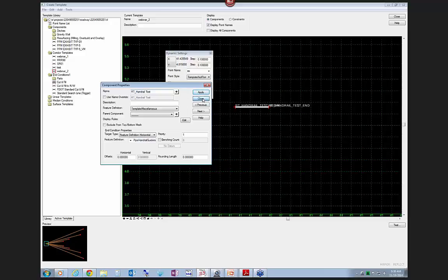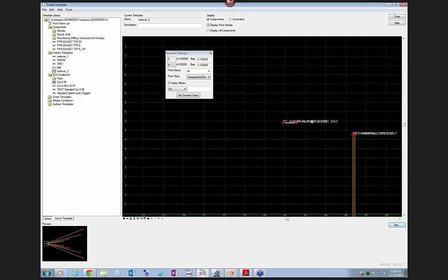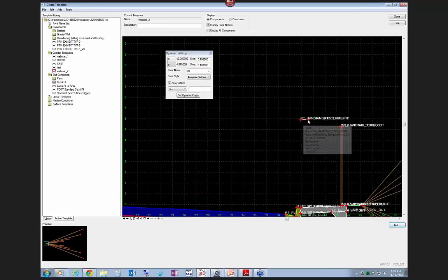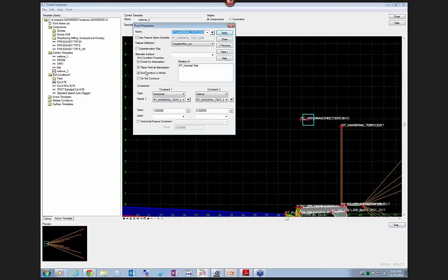And so if you wanted to test that one, now that I've got it to where I can display it, notice that the endpoint has a priority, where the end condition is infinite. This overrides whatever horizontal distance or constraint you placed on there. If it was not infinite, then it's only going to look for a pipe rail within these limits for a target, which would be from the back of curb to 1 foot in front of the curb.